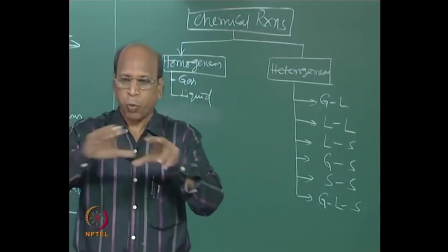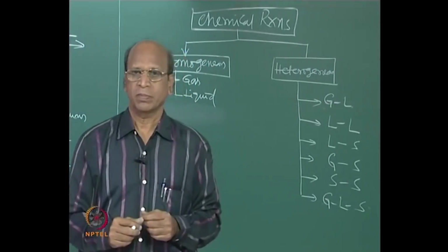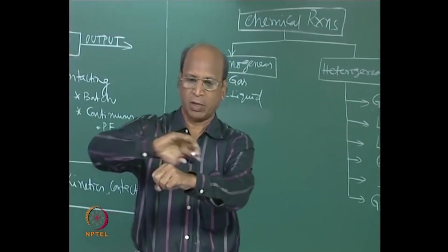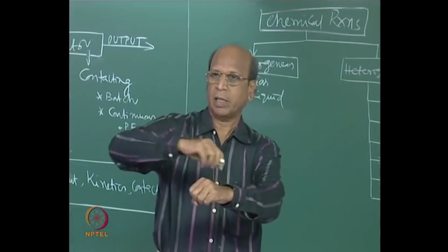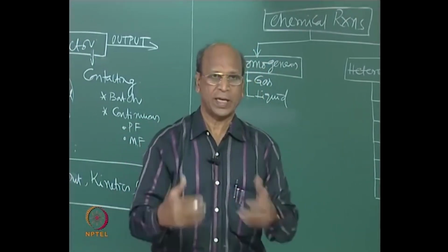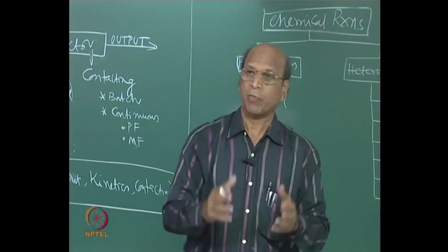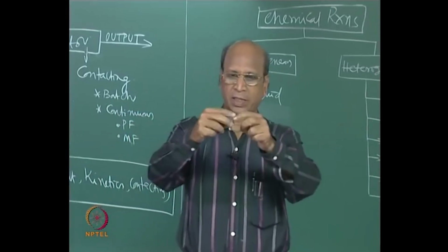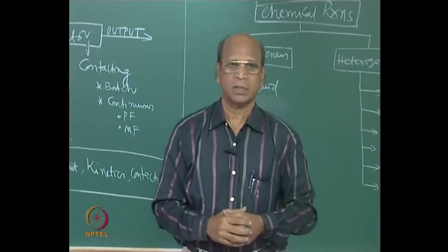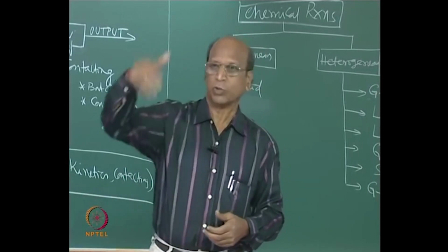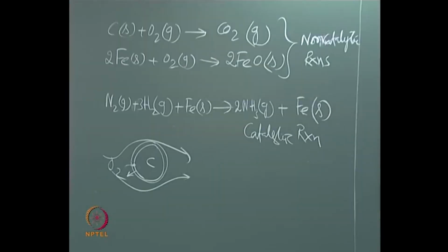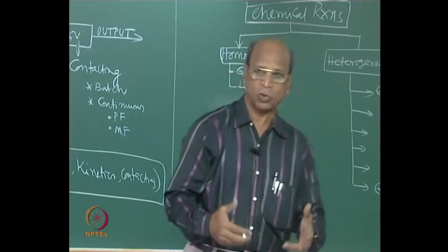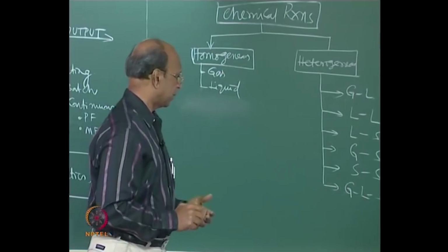That means your porosity inside that bed is not uniform. One particle this side, another particle this side, another particle this side, and when one particle is here, one particle is here, all this is vacant space. This is the diameter of the tube. So, that is the reason why that uniform flow will not be there. So, that is why wall effects, minimum number of particles you should put across a diameter will be 8 to 10 particles. Okay? Along the length so many particles, all that I will tell you when you are coming to RTD and all that. I mean, these things will come there. Okay? So, all these things also we have to keep in mind when you are finally designing.